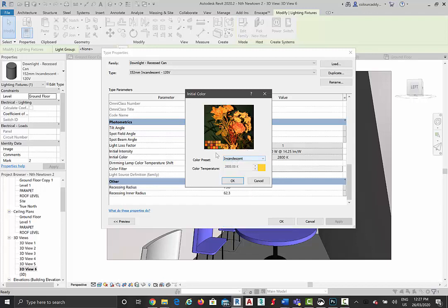And you might think, well, why do we need to even worry about temperature? The reason you do is because the temperature controls the color of the light. So again, low temperature values like this, 2800, give you warm colors. So orange, and when you get very low, it actually goes to red. But with the values you'd be dealing with, it would mostly be orange. Let's see if we make it a bit lower. Here we go, 1800 is minimum. So 1800, again, that's almost red, but you can see still, obviously, is orange. So that is the lowest you can go to.